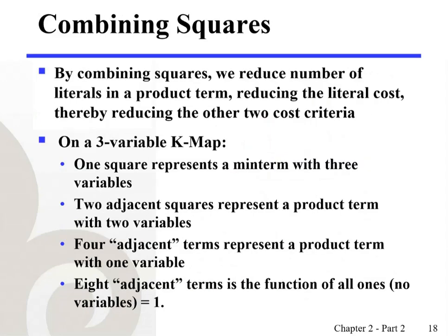Now we have some ideas on how we can construct K-maps from truth tables, and each cell of the K-map represents the minterm locations of the function. Now, remember that we wanted to minimize or optimize a Boolean expression in terms of, let's say, literal cost and gate input cost. The K-map, we said, is the graphical way of obtaining the near optimum Boolean expression with a minimal cost.